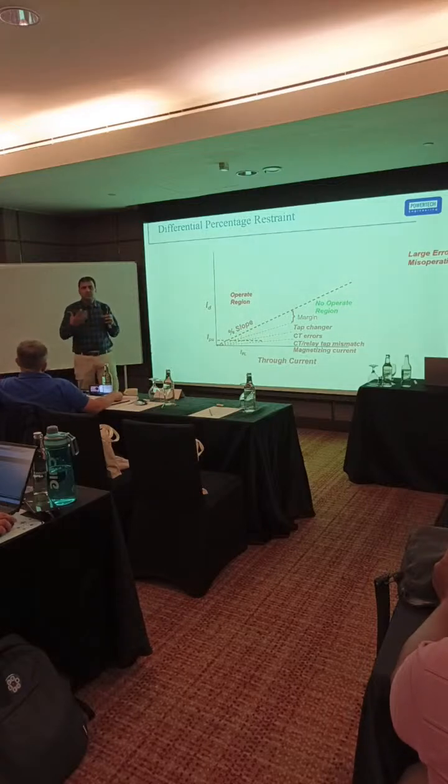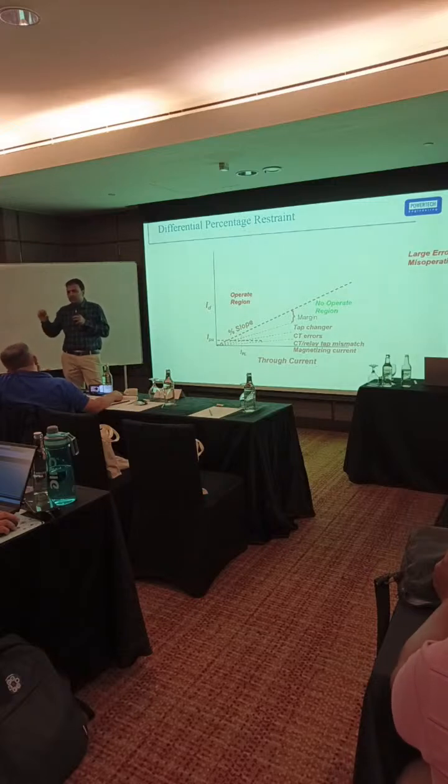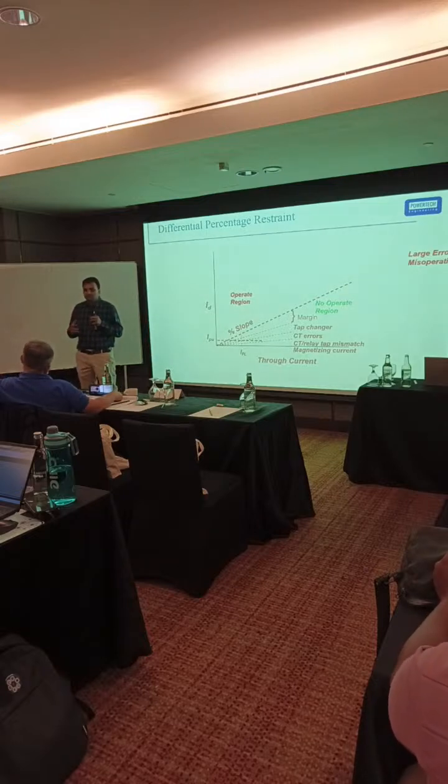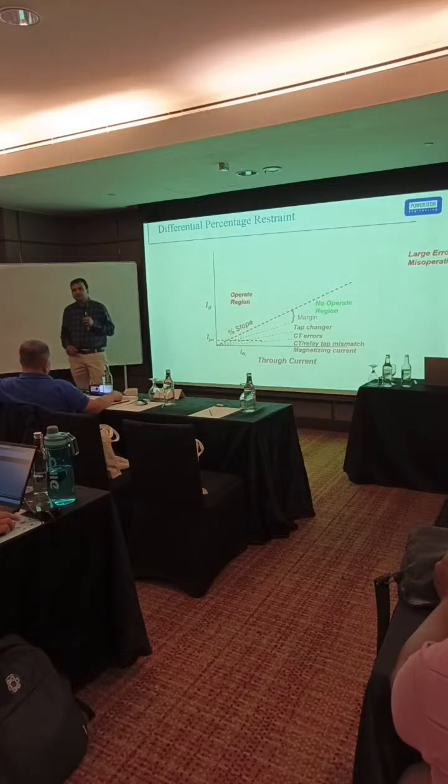During charging, all three phases will not have equal magnetizing current, so there will be unbalance, and if your setting is low in the SEF, that may cause tripping. So many do harmonic blocking in that case also. These are the few factors which can trip the transformer during charging. SEF is standby earth fault.